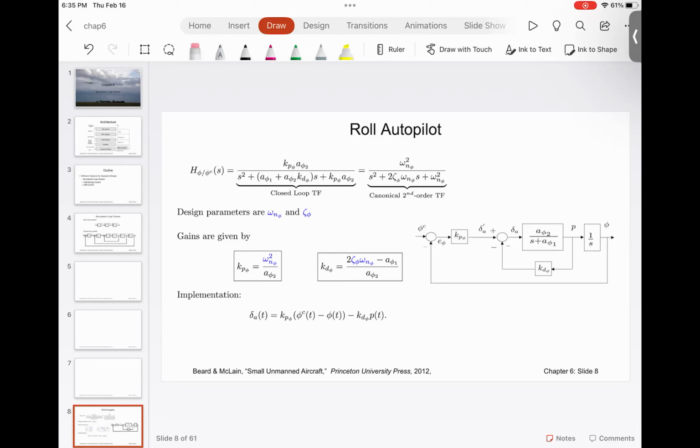For example, have you seen the shocks of your automobile? You have a damper and a coil spring. So you could have an integrated actuator with the spring and the damper, actuators that change the preload on the spring, and valves that control the fluid flow, so you can tune the damping coefficient. Everyone understood this? So that is how it is done in practical aircraft systems.